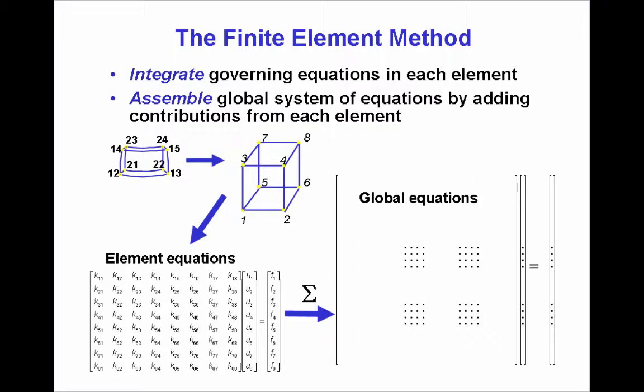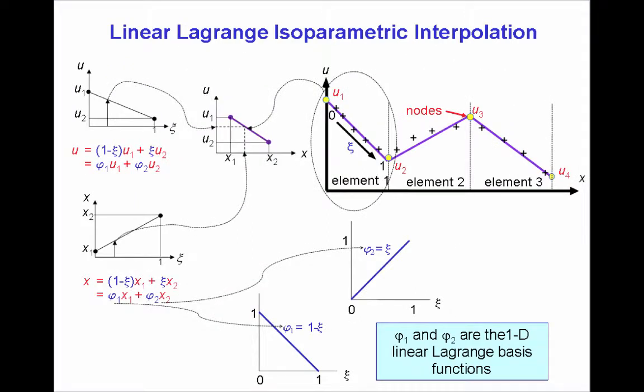Continuity supports a variety of basis functions for isoparametric finite element interpolation. The simplest type of elements are piecewise linear Lagrange elements. Note that within each element there is a local finite element, or xi coordinate, that also varies from 0 at the first node to 1 at the second. The parameters of the linear interpolation are the values u1 and u2 of the function at the nodes, and thus the basis functions phi1 and phi2 are the corresponding linear functions that, when multiplied by u1 and u2 respectively and added together, result in the linear interpolation between u1 and u2.